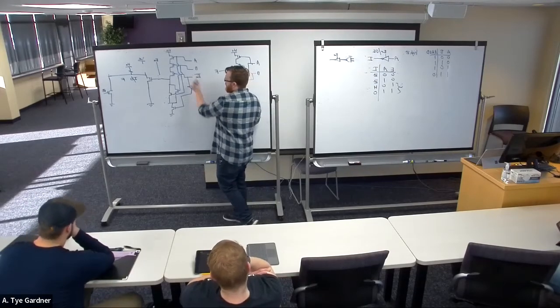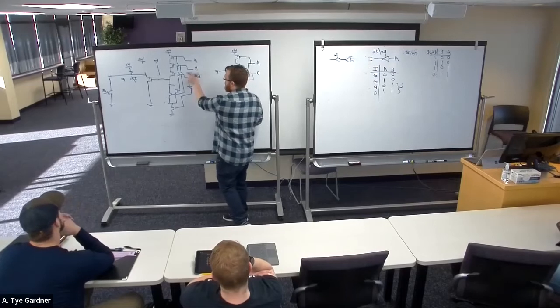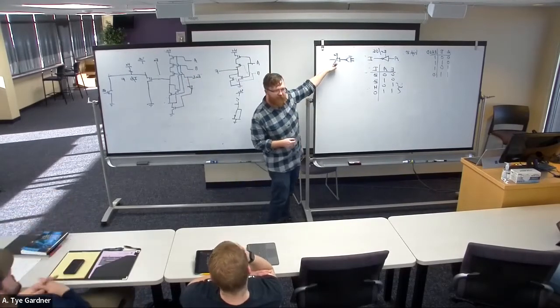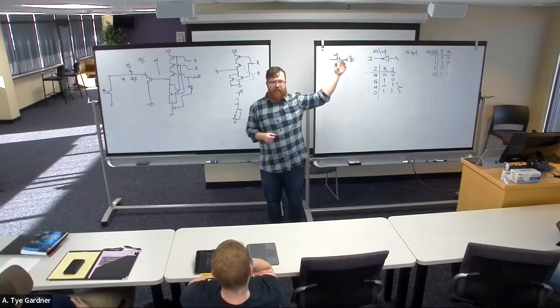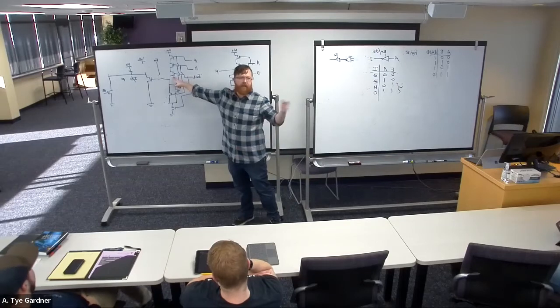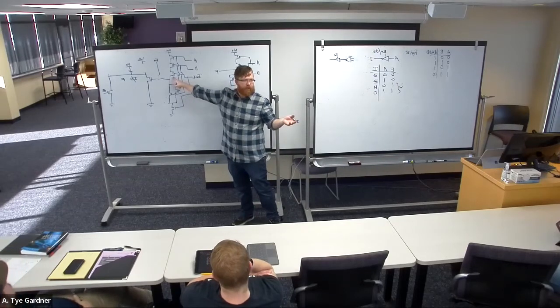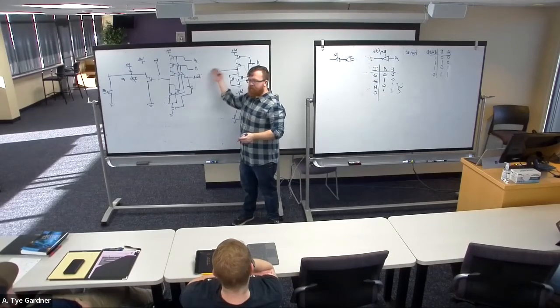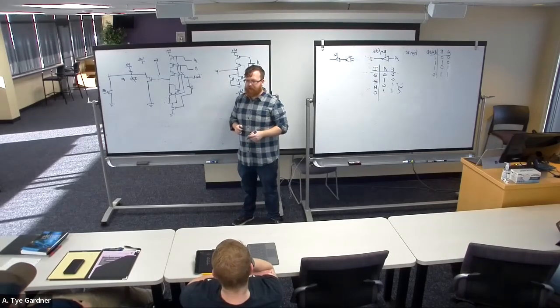Realistically, this is not enable, or in other words, enable dot low, right? This is an active low enable. That means it has this little bubble on it because a 0 turns on this circuit, allows this circuit to work. Does everyone follow that? Maybe? So you could just put another inverter at the beginning and just be active high. Yeah, you could throw that in through an inverter and make it active high.